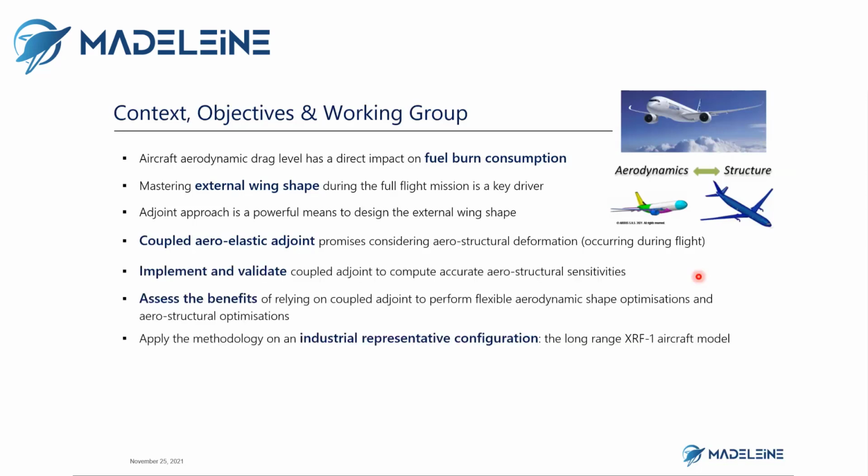So the objective within the Madeleine project was to implement and validate the so-called coupled adjoint in order to compute accurately aerostructural sensitivities and to assess the benefit of these new capabilities to perform either what we call flexible aeroshape optimization or aerostructural optimization. Romain will explain in deeper detail what it means and what the assumptions behind that are. And then to apply the methodology on an industrially representative configuration, as explained at the beginning, the long-range XRF1 aircraft model.